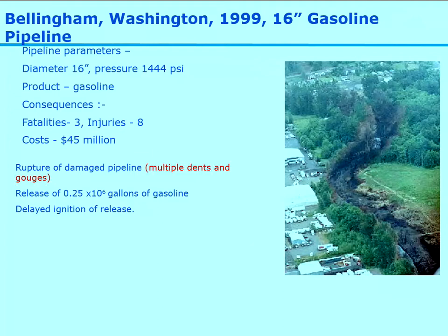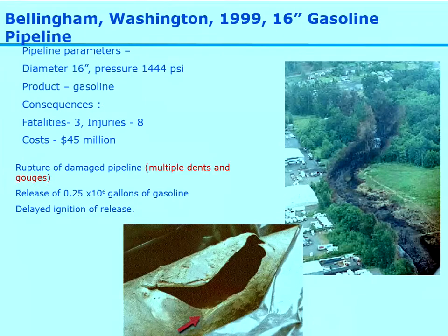Now that is a picture of a typical rupture in a liquid pipeline. So you can see it looks very different to a gas pipeline. Basically, ruptures are defects which are not stable. So during the failure event, the defect will grow. You can see this has grown, but it's very quickly ringed off and stopped. That's because in liquid pipelines, as soon as you have any sort of damage or release, the pressure drops very quickly. That doesn't happen, of course, in gas pipelines.